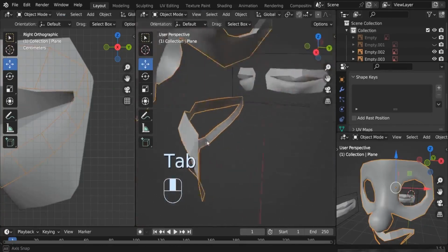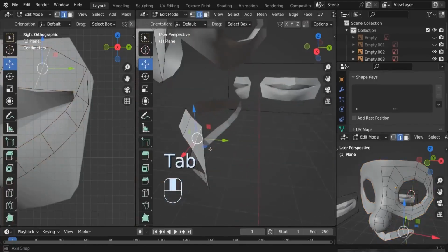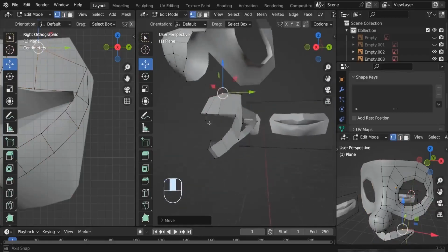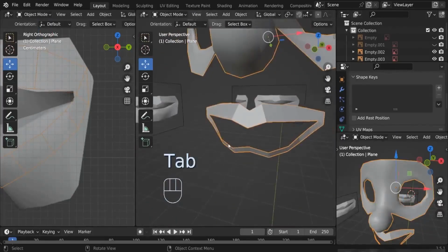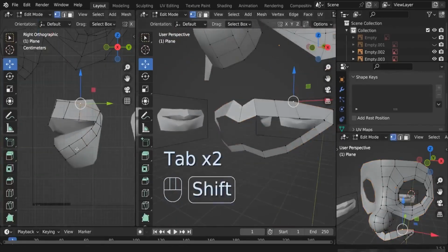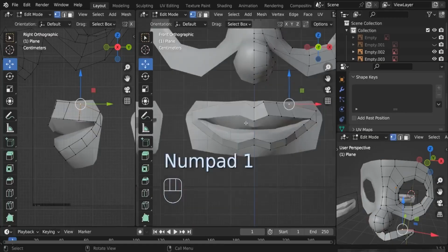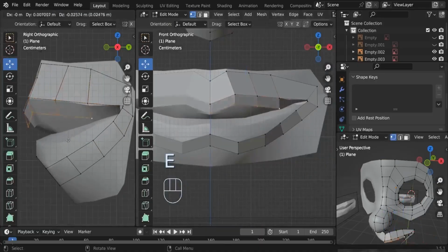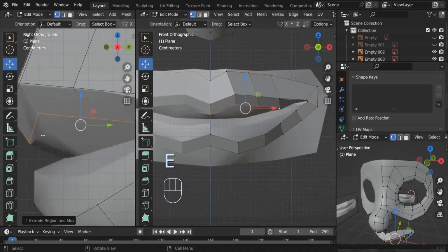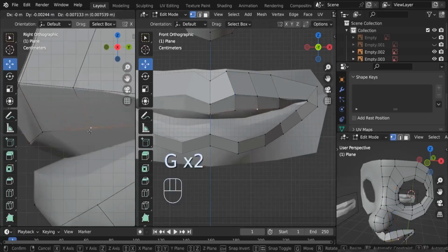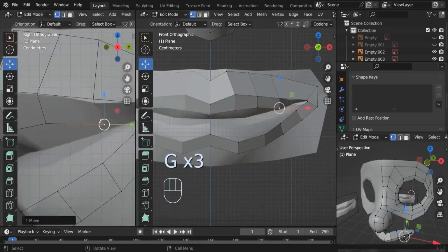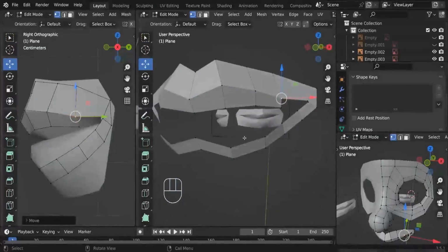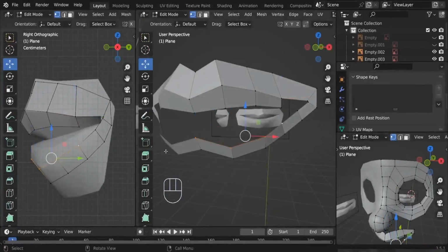You can try to investigate the shape. For example, this vertex, we might want to move the top a little bit forward. All right, seems right. All right, so let's work on the inside. So here for the inside, I'm gonna press 1. I'd like to grab these vertices and we can extrude them. For example, here to this area. Also, we can drag these down like this. We can take this one down a little bit. Perfect. Let's check that out. It looks perfect. And also here, we can do the same thing.